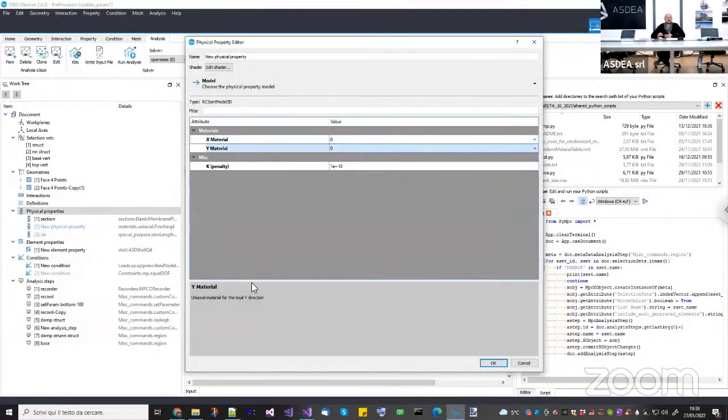Local X direction is the local X direction given to the joint itself. What I'm assuming here is that the joint always has a 90 degrees direction. Now the only problem is that if you have beams which are not at 90 degrees. But actually, I think we can change it because it is not necessary that the material are actually in a triad, but that is the typical approach. Is your problem that your node is oriented in a different direction, or that the beams that converge to the node do not have a right angle?